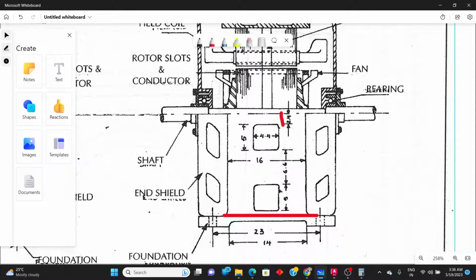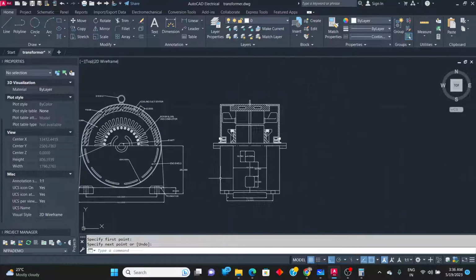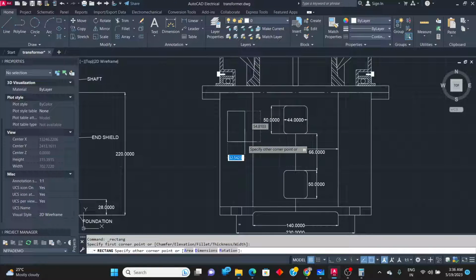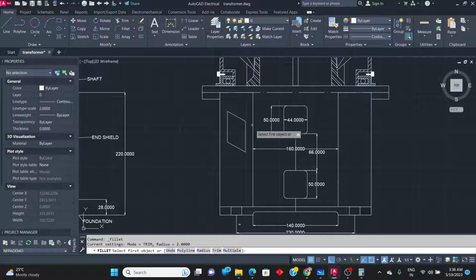So again, this part, these two parts are there, right? So simply what we'll do, one portion will take and we'll draw like this. Select this. Now fillet will take radius, will mention 2 was there and I'll make it 6. Okay, and option I'll take multiple.